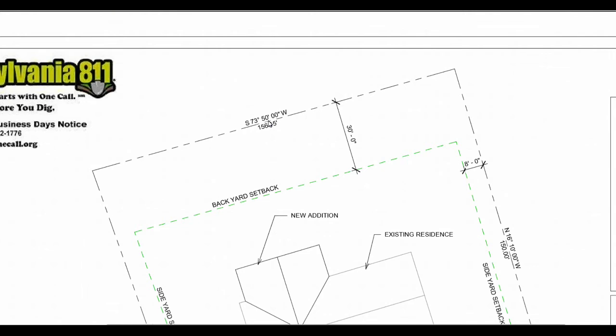So if I were to make a mistake by 1 degree over 5,000 feet, then it's going to make a significant difference whenever the total size of the property is determined. So I can break down 1 degree even further by having 60 minutes within that degree.